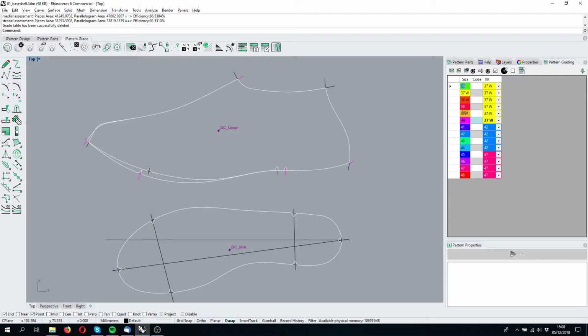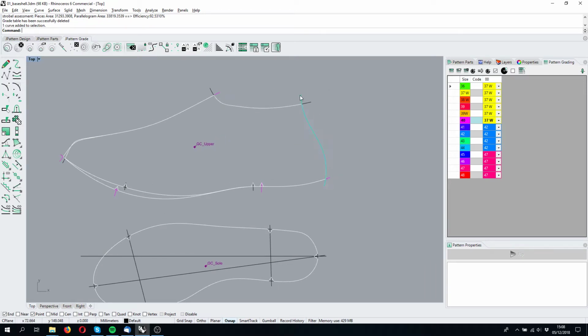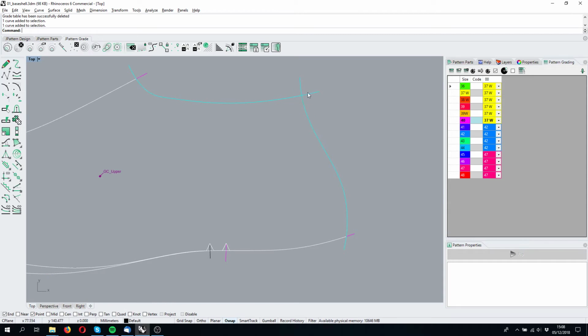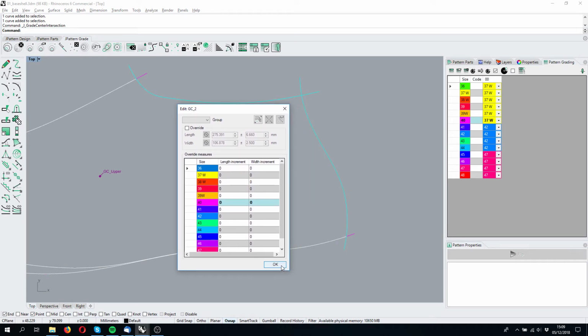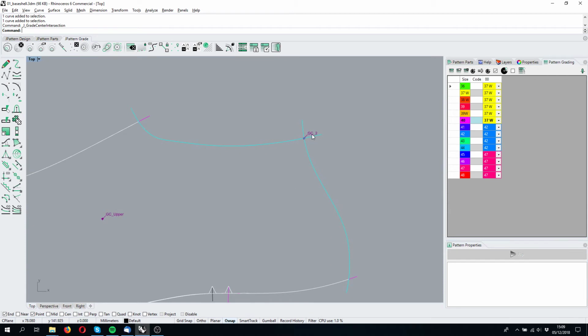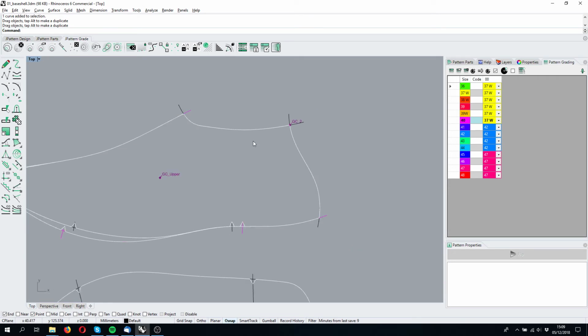And the last thing that I want to show you now is the possibility of creating grading centers on distance and on intersection. Say that now we have these two lines and we want to create a grade center here in the intersection of these two lines. We can easily do that by going to the grading center of the model, and as you can see we can right click on here and the center is added automatically. If we move this line, the grade center will follow.